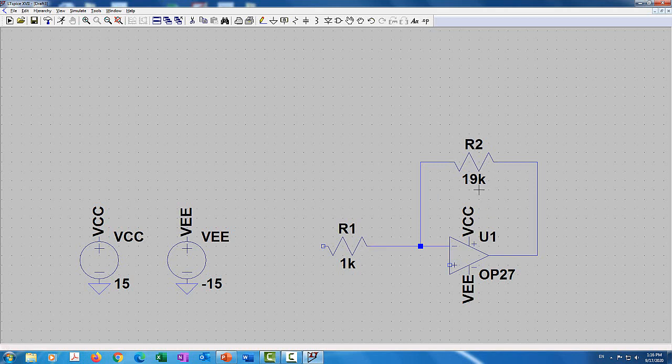So any of the resistors here have to be bigger than 500 ohms. In reality, that depends on what your Vout is. If your Vout is going all the way to 15 volts, you might even use a 1k ohm resistor as a minimum value. Another thing is that you can't use very, very large resistors.